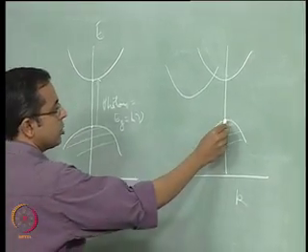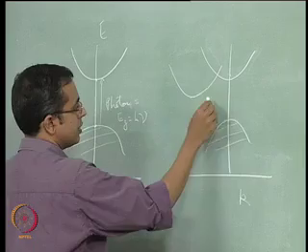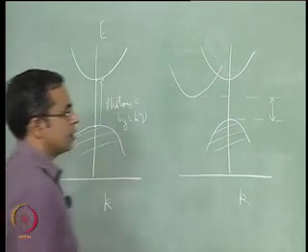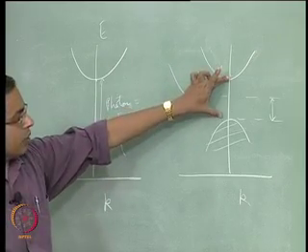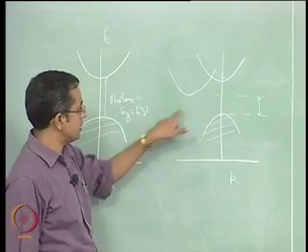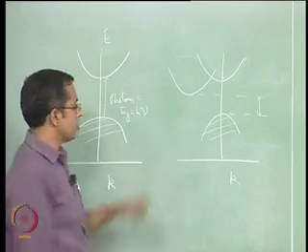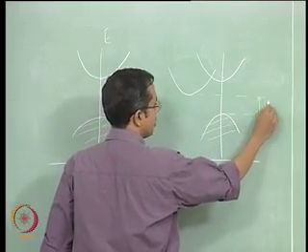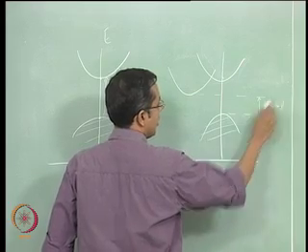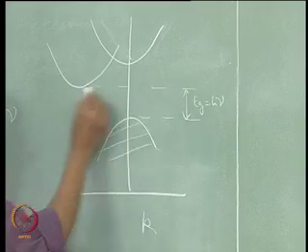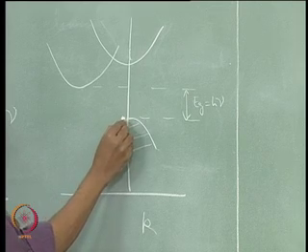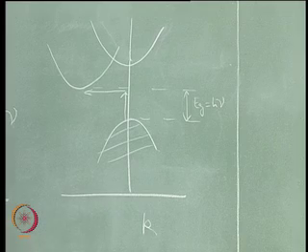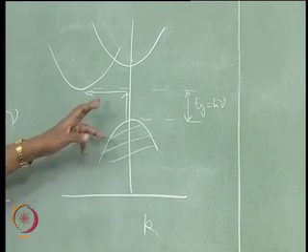So now you need less energy, this band gap is smaller than this band gap, only this is at the same location in K space and that is at a different location in K space. So the electron needs less energy to go up here, this is a smaller Eg, but it will not suffice if it goes here, it has to go across to this location in K space. So two things have to occur: it has to go up and it has to go across.